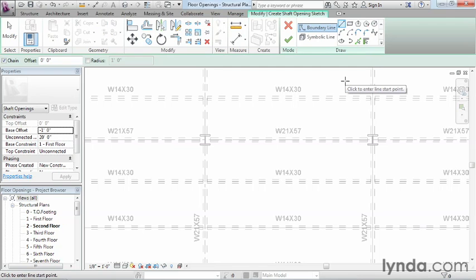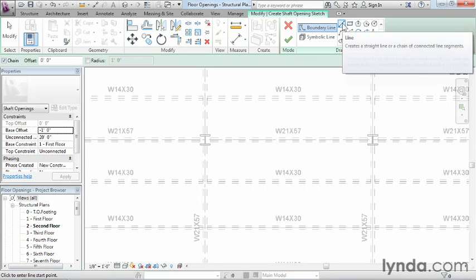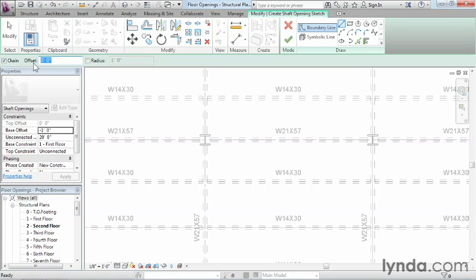Next, we'll want to start to draw this in. Now, I happen to know that this happens to start off about 1 foot off of where this beam is placed at. So in order to be able to do this, we'll start off by using the line work tool, but we're going to set an offset value to this line work tool. So when we start to draw, it's going to actually place this first line 1 foot away from where we're drawing the line at. So we'll select Offset 1 foot, pick the beginning spot for where this line should be, and then move straight down. If for some reason the line is on the other side, it shouldn't be for you, but if it is, you can always hit the space bar to flip it to the appropriate side.